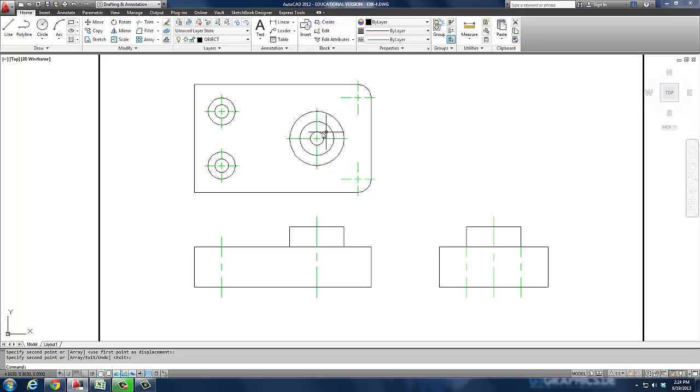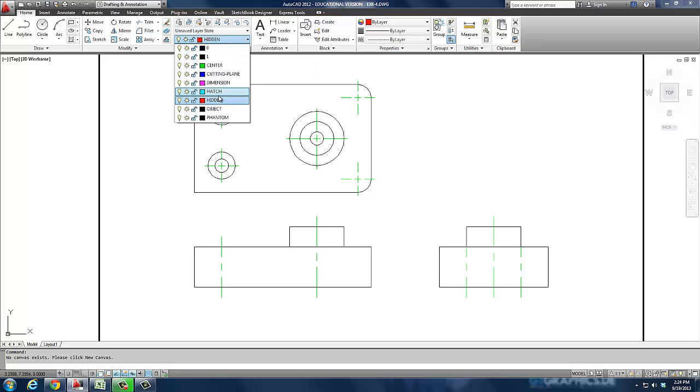But I've got to have 2 more concentric circles. So what I'm noticing is that if I do a line, I'm going to change my line to my hidden line real quick, because these are cut holes. Okay, and actually in your text, step number 6 reads to set your layer to hidden. So instead of typing LA set hid, I pulled this down, I picked the hidden.